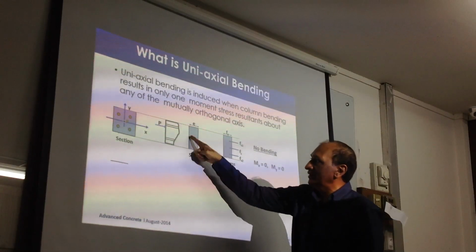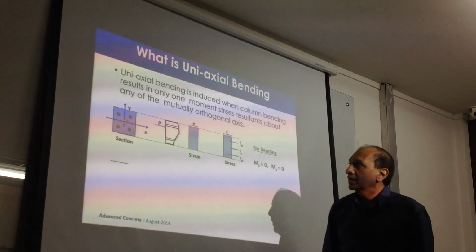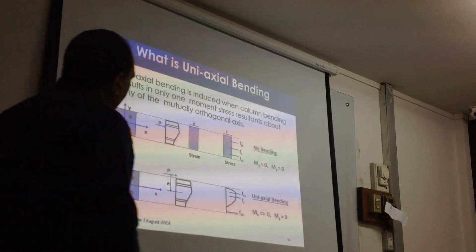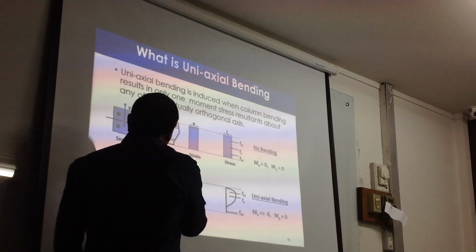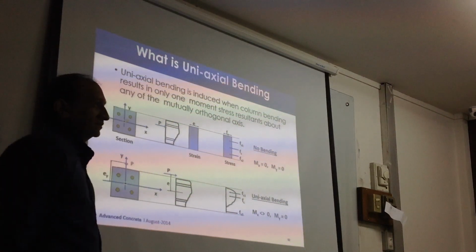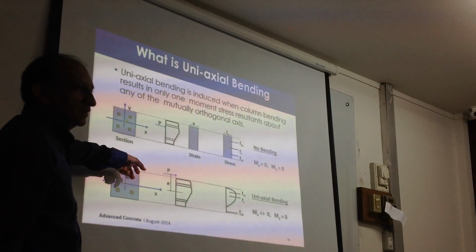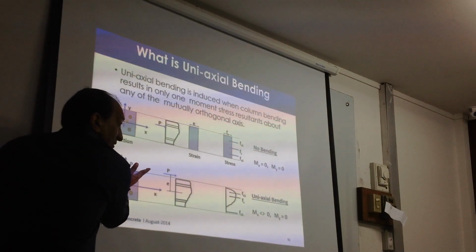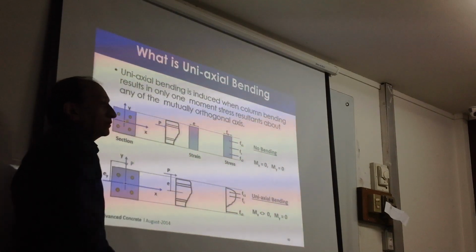So this is a case of a symmetrical section and no bending. You can see the strain will be like this, 0, just pure compression on this one. This is a case where you have eccentricity of load, and then you have a stress strain curve like this. We call it uniaxial bending because the P lies directly on the y-axis. So the bending is about the x-axis, which is horizontal, correct? But if I move the P here, this angle of bending will change like this, and the section will bend like that. And if I rotate it back, then it becomes a uniaxial bending again.